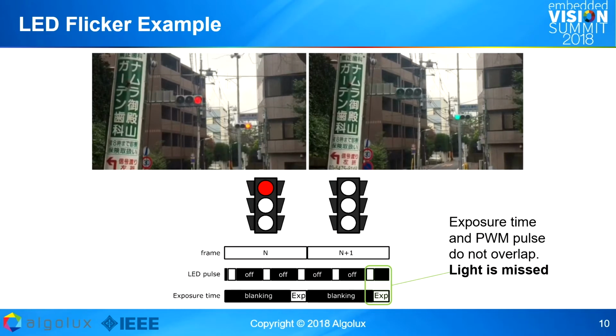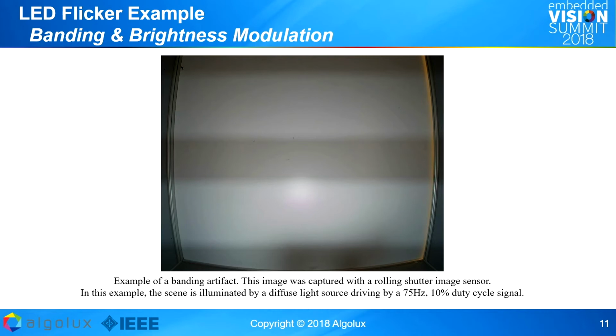But the important thing is that there first also has to be a method to measure and characterize flicker and how it affects image quality and computer vision. There's even a further subtlety to this if you think about rolling shutter cameras, and this of course also affects not only the temporal behavior of the capture, but also spatially due to the rolling shutter exposure in the camera. We can get quite severe streak artifacts in this setting where we have a fairly uniform LED illuminated backstream.